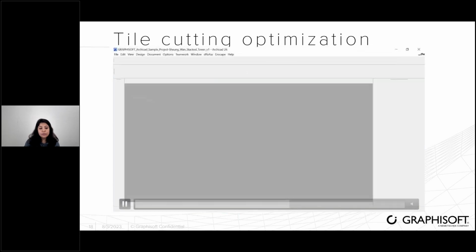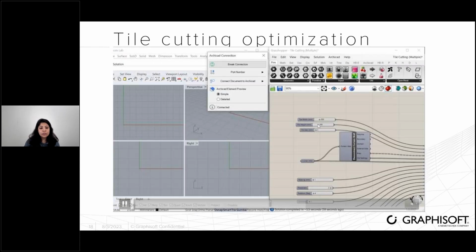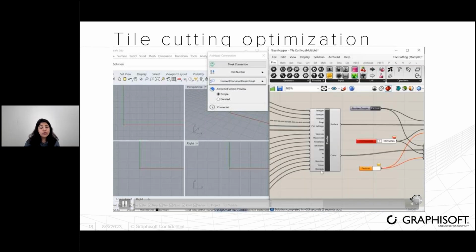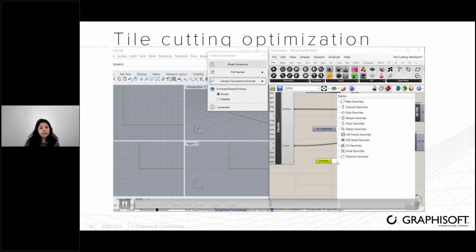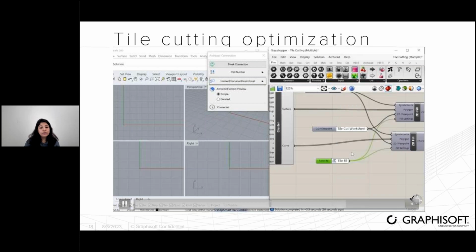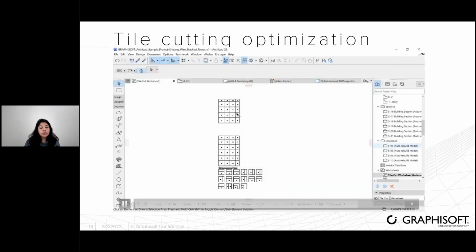For the curtain wall, we will be getting the curves from Archicad itself by selecting both the curtain walls together and passing them to the node inside Grasshopper, and the cluster will take the parameters from there. The next thing is simply to assign the worksheet that we have created and also the favorite for the fill. And then just run the script.